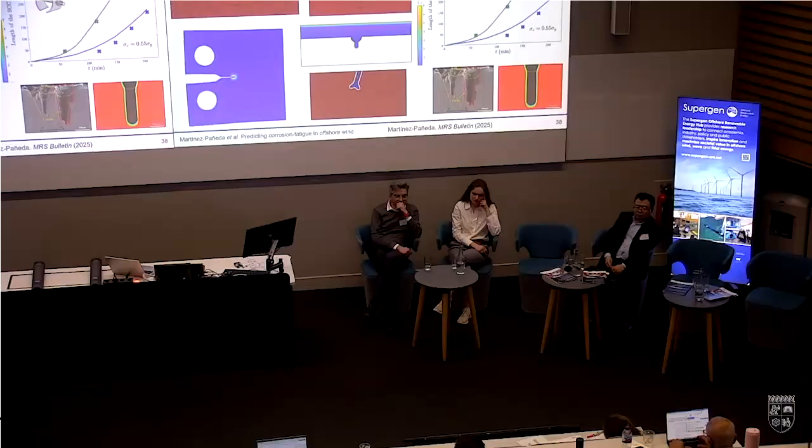So you can basically solve this corrosion fatigue problem from mesoscale first principles, without making any assumptions, without relying on fitting parameters. You are solving things as they happen in reality. You have electrochemistry here, you have mechanics, you have microstructure. And this is fundamental work that I did during my Future Leaders Fellowship, and I demonstrated that these models were able to predict a wide range of experiments in corrosion and fatigue across a wide range of materials.